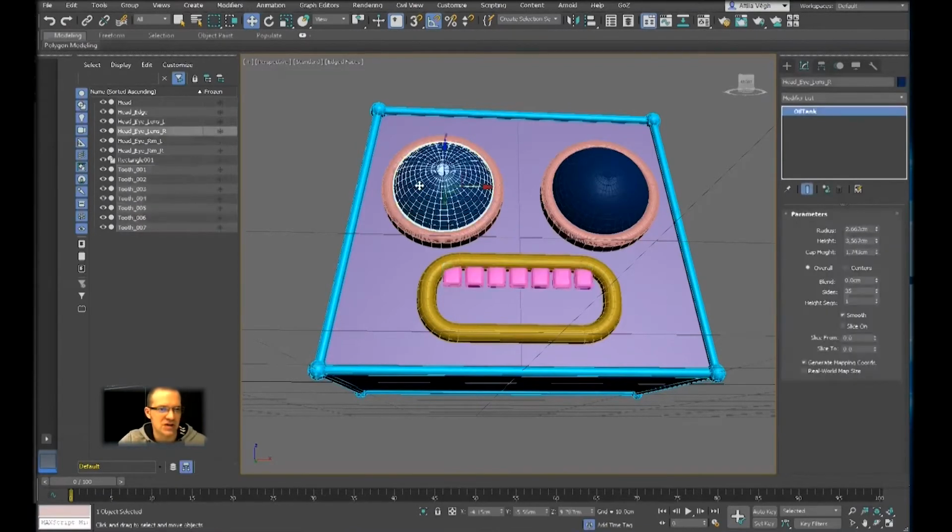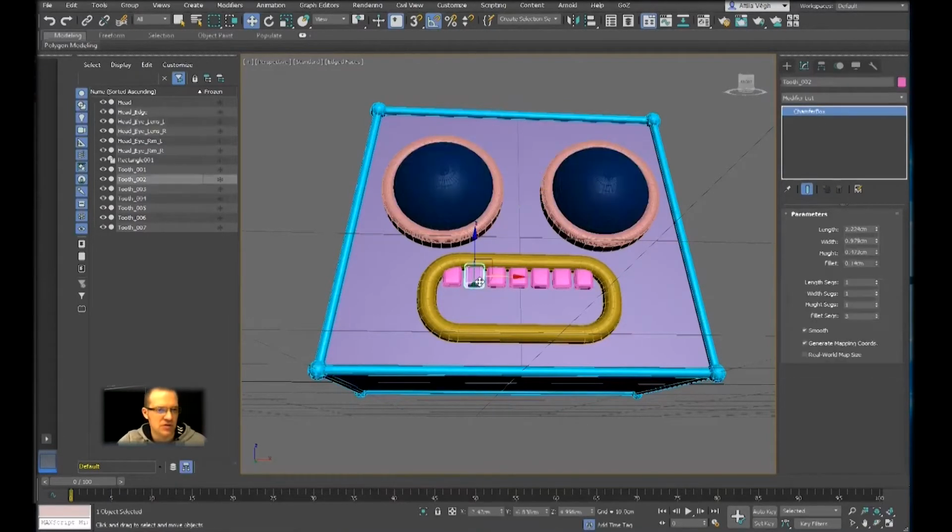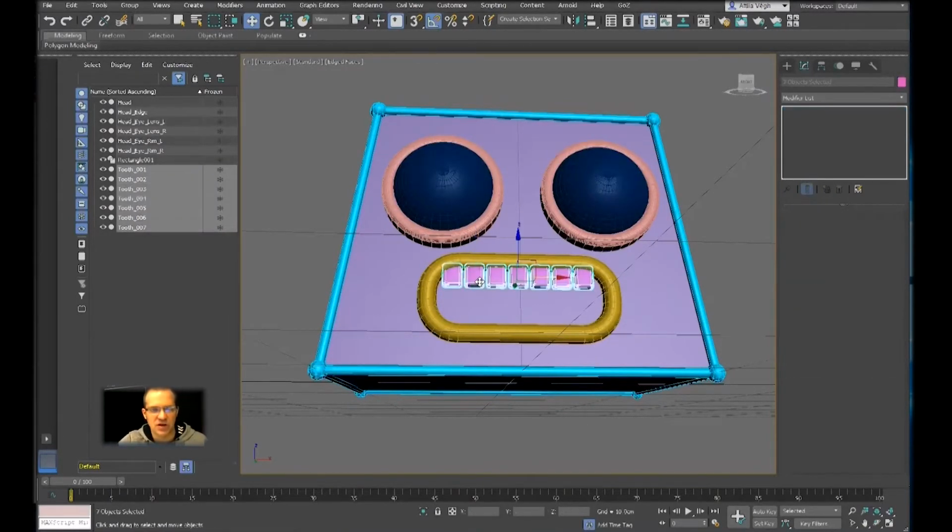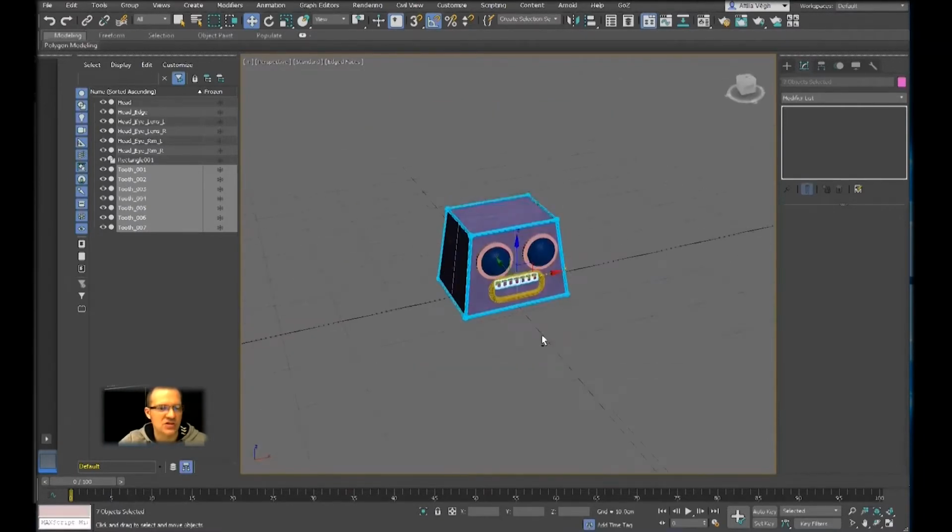I can select this eyeball and give it a try. Ctrl Q selects the second eyeball, because it is a similar object. Same with the tooth, Ctrl Q selects everything. Now, a very practical piece of advice: make sure you have your selection correct. I like to move it away to make sure that nothing else is moving, nothing else is selected, it's only the teeth. Then press undo.